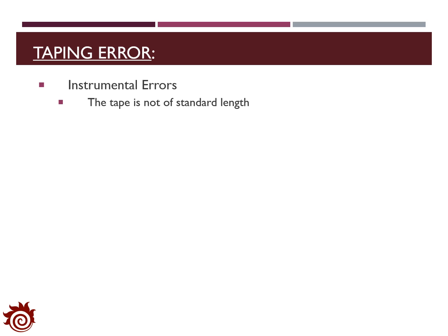measure any distance accurately. The second one is called a natural error, including the errors from the temperature, tension, and sag. We know that usually with the temperature, we will observe expansion or contraction to the tape, which will generate some errors for the taping measurement. Applying tension to the tape will usually reduce the readings from the tape, while for the sag, which is usually caused by the weight of the tape itself, it will actually increase the readings from the tape.